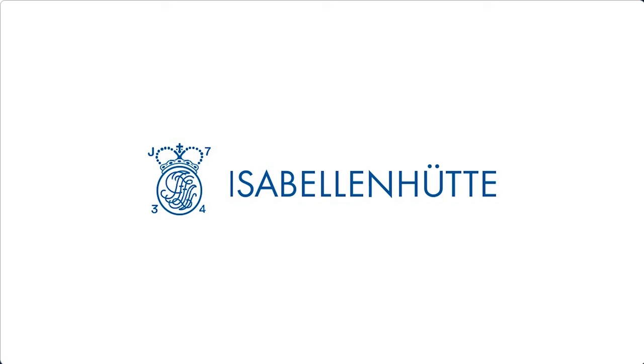Yeah, thank you. I tried to touch on that a little bit in the presentation too. So there's definitely a trend for a higher safety rating on component level in the future. The reason for that is simply to make the life of the OEMs easier, basically. If components have a higher ASIL rating already, that eliminates the need for redundant components and saves cost, and it also facilitates achieving higher ASIL ratings on system level, or achieving the ASIL D rating on system level. And that's basically the main reason.